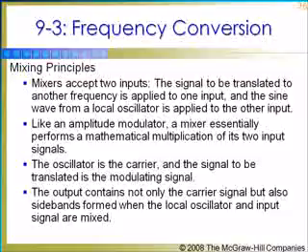Either the sum or difference frequency in the output is the desired signal. To translate the input signal to a lower frequency, the lower sideband or difference signal is chosen. The local oscillator frequency will be chosen such that when the information signal is subtracted from it, a signal with the desired lower frequency is obtained.